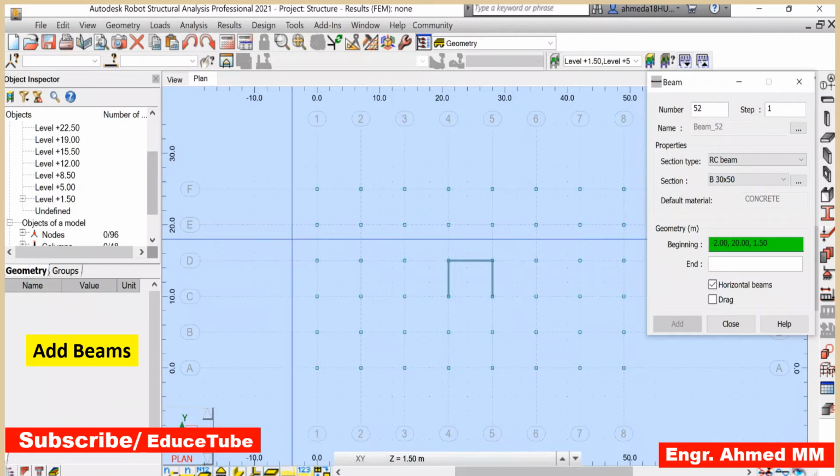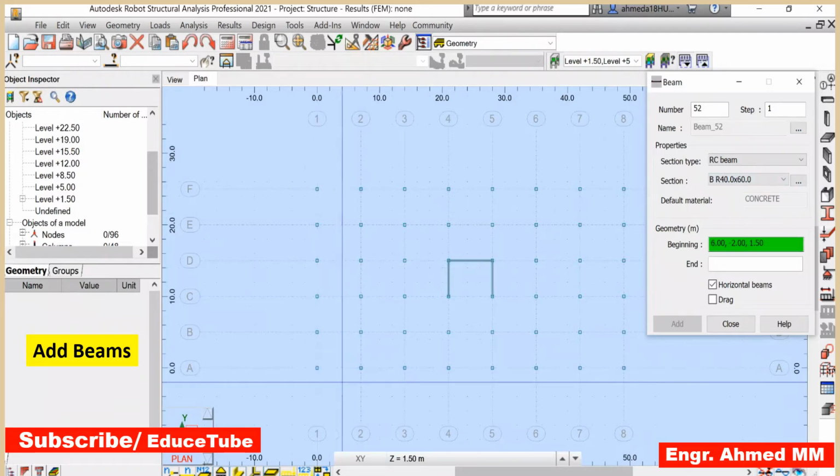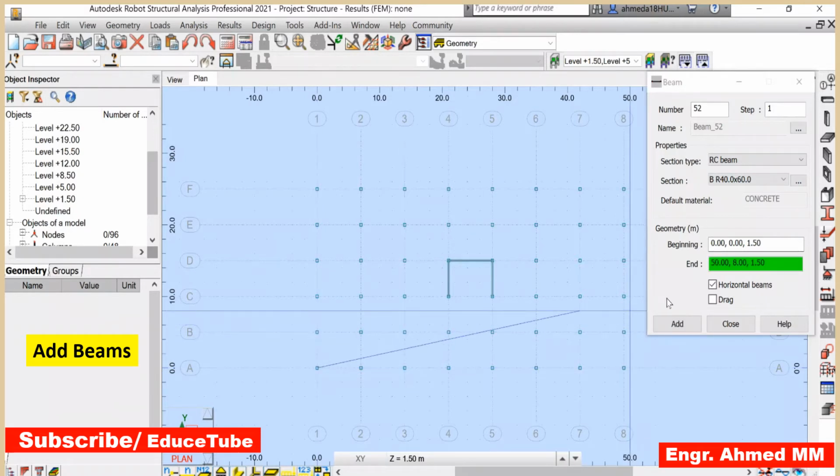Now the cursor is active, so I can put this beam, not this one. I have to change it to 40 by 60. So start from here and make sure this drag is on, so you can draw it in one line, 1, 2, 3, 4 and 5.